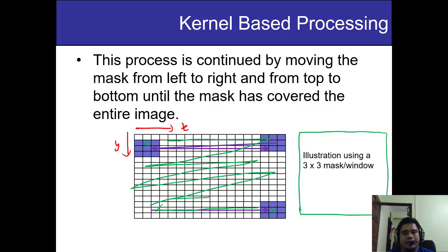Okay, now the sliding seems to be very clear. We need to do a sliding process because it is one of the processes involved in convolution. But the issue is, in this discussion, why do we skip the flipping process? Because in one-dimensional convolution we need to flip either xn or hn.